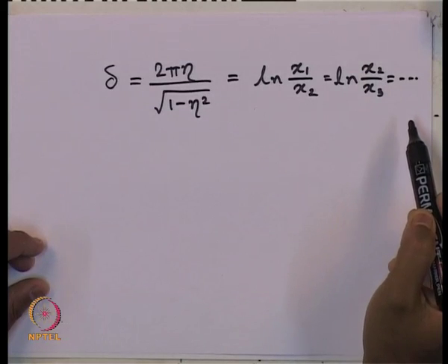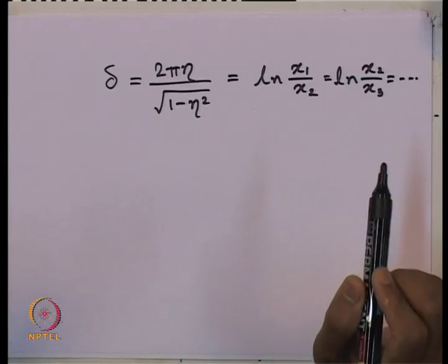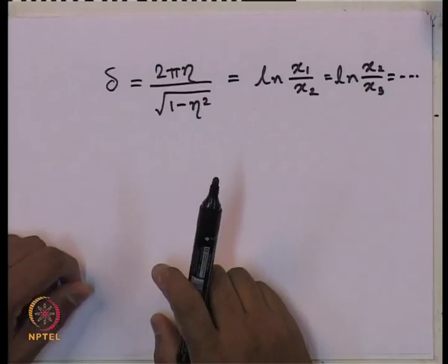But now, the problem that can arise in this case is that when the system is undergoing free vibration, it may be difficult for us to note down the displacement at every successive cycle. While recording the reading, because of manual error or things like that, we may miss some cycles in between. So, if we try to take the amplitude in successive cycles, that is first or second or third, it may be possible that we miss some of the cycles.